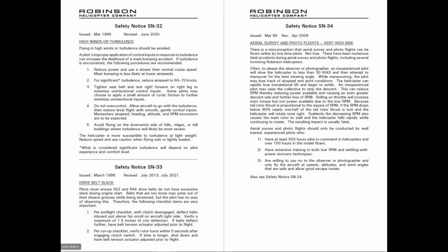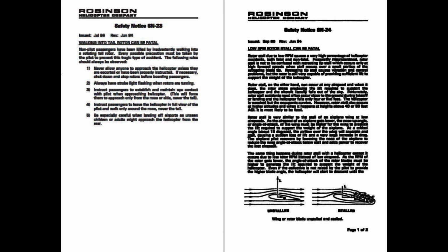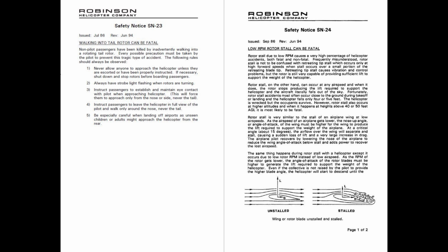The tachometer will slowly drain the battery. During a low-speed flight, the pilot loses translational lift and begins to settle. What should they do? The pilot should lower the collective and increase the throttle. Once the engine is above 90%, a slight forward cyclic may increase the speed. If the pilot applies forward cyclic before reaching 90% RPM, they may lower the RPM to a point of stall.